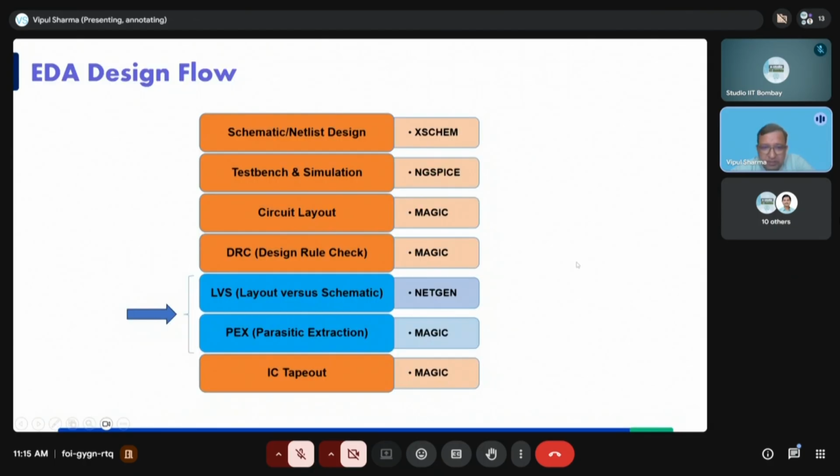So this is the journey which I talked about. Once the verification is done, if everything is okay, your specifications are meeting and your design rule checks are clear, then it is ready to be fabricated. When I say ready for fabrication, it's not like just doing a layout of your op-amp and it is ready. There are some other steps, but they are more procedural, like building an IO pad or IO ring around the circuit. These are standard things which come with any technology or are available with the PDK. The only choice the designer has to make is what kind of IO pads they require.